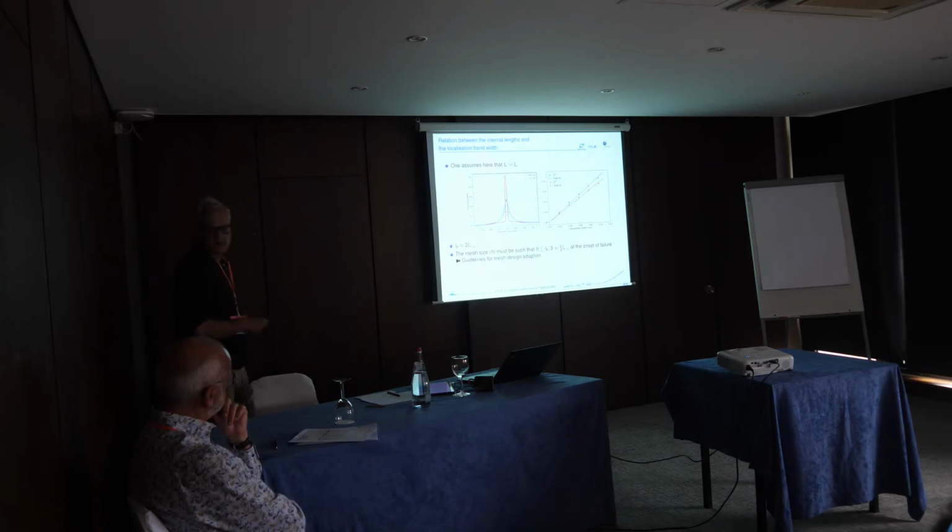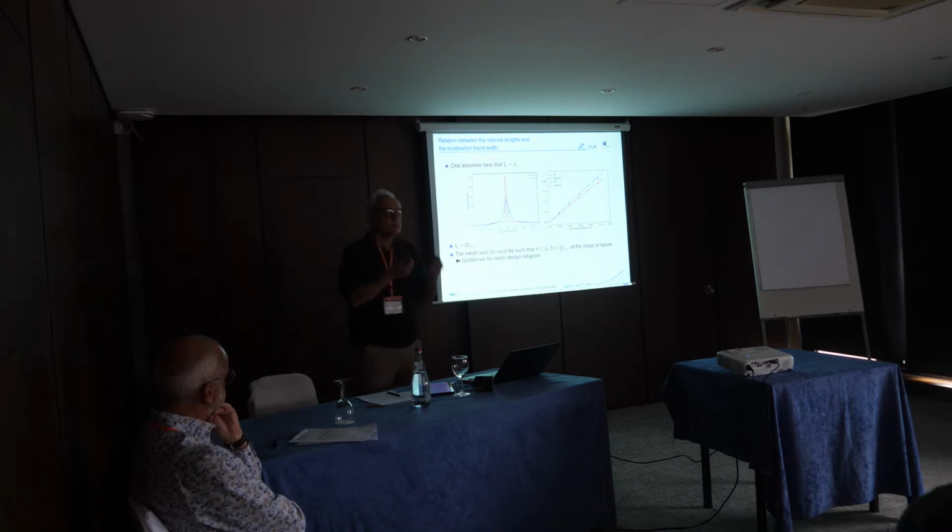The red profile is the local variable, which is not regularized and which is localized here within one element. We did the study for plane strain and axisymmetric. Roughly speaking, the localization band width is about 2 times the non-local size you incorporate in your model. And then you have to worry about the element size, because you need enough elements within the localization band so that you can discretize it.